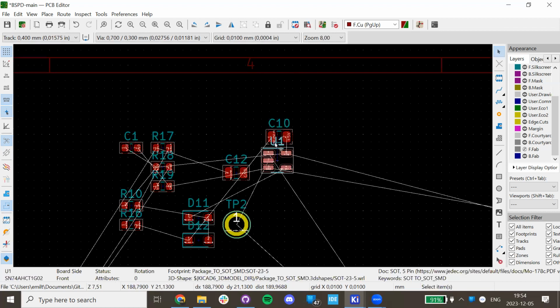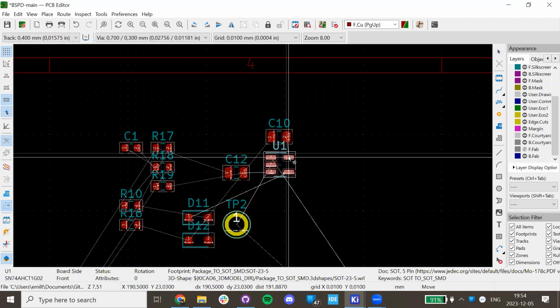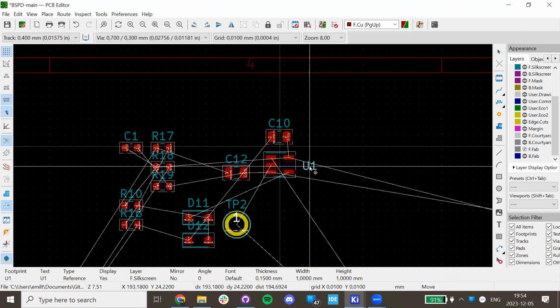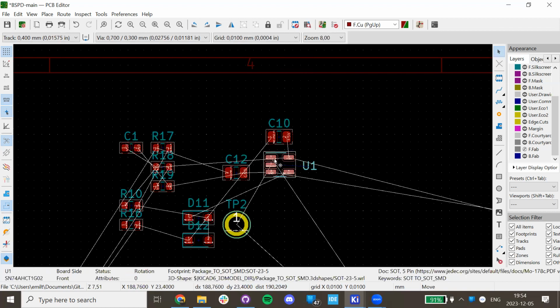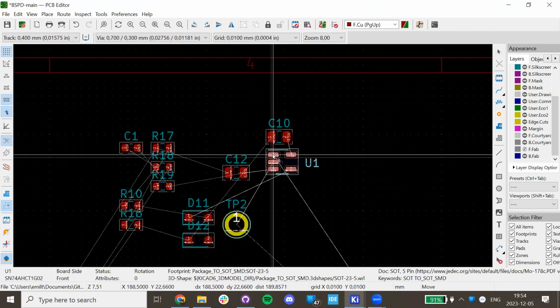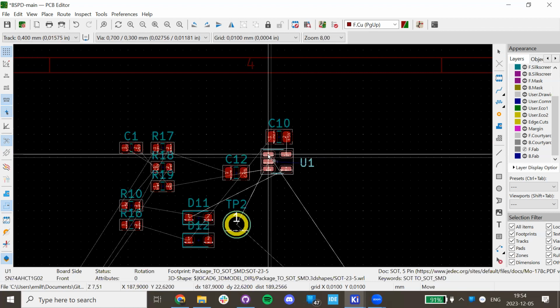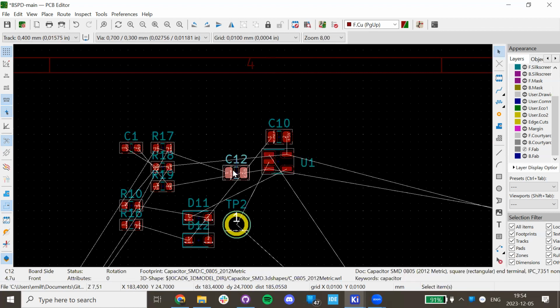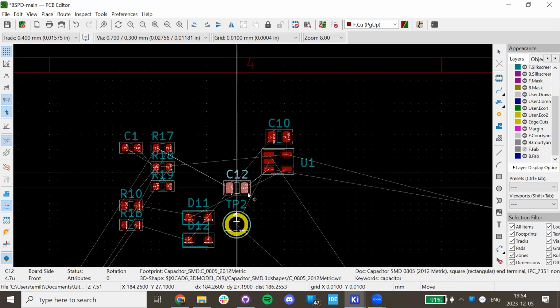What they do is they have a piece of glass fiber covered in copper on both sides, and then you apply a photoresist, which is just a coating of material that is sensitive to light.